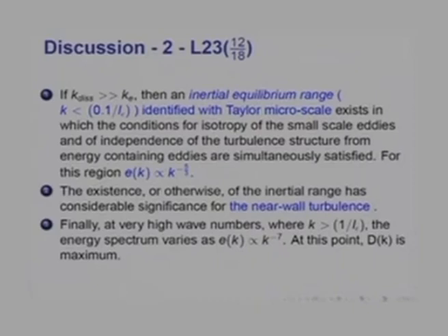Now, this is very important. Many experimentalists always want to ensure whether their turbulence is sufficiently vigorous so that they can take it as fully turbulent or not. This means: are the large wave numbers where dissipation takes place and the small wave numbers, the energy containing wave numbers where the production takes place, sufficiently separated or not?